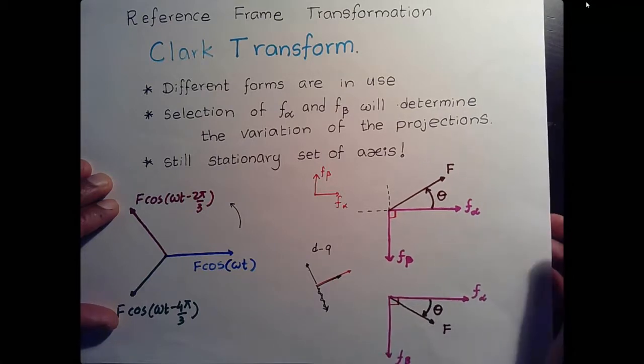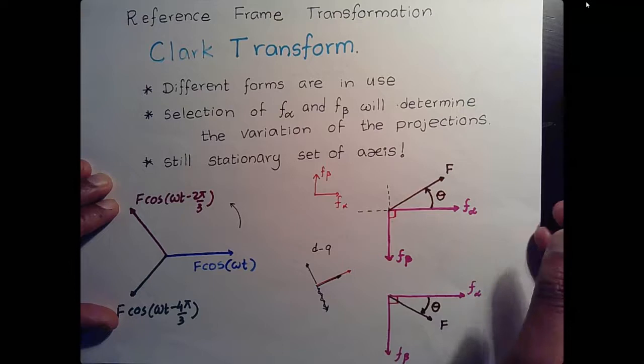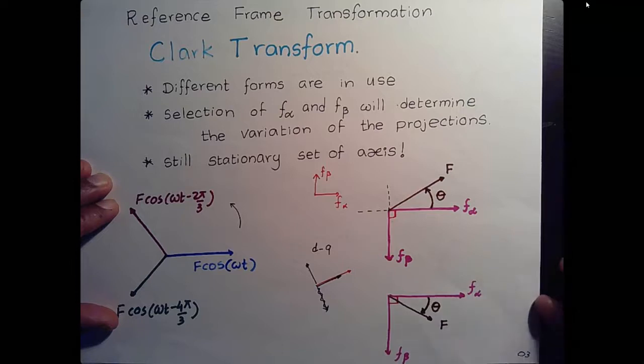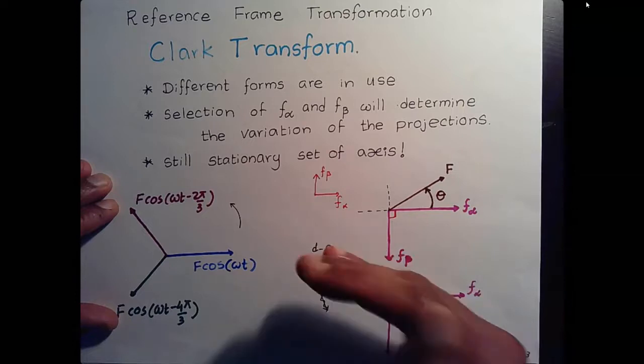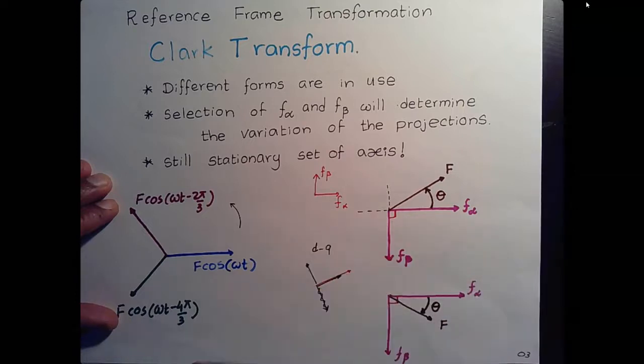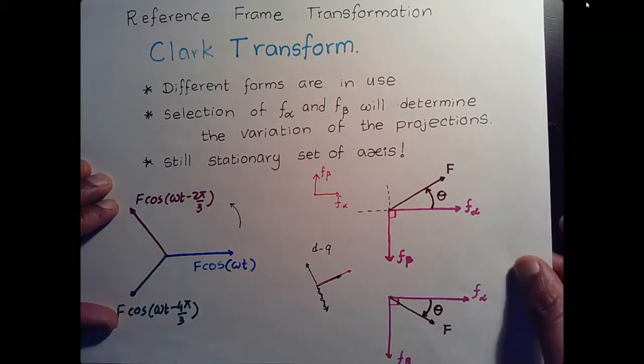In synchronous machines, we typically define the rotor flux along the D axis, and then we apply the Q axis, which is the stator flux, 90 degrees out of phase to generate optimal torque. There's no saliency. Just keep that in mind.